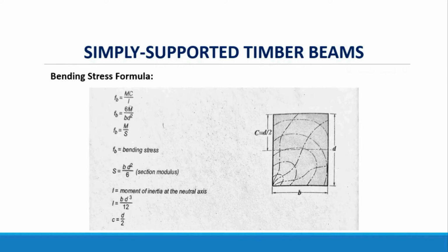For a simply supported beam, typically you need to use the shear and moment diagram to find the maximum value for moment. And you can use that value for M in this formula.